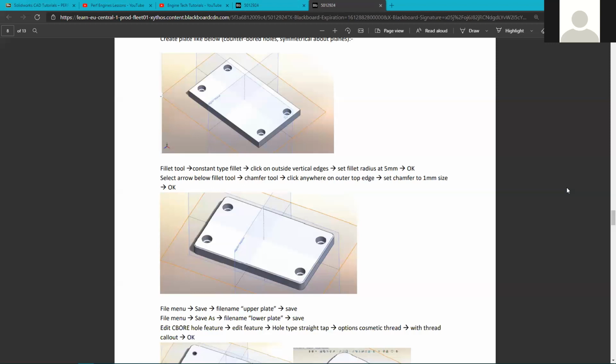But as a last ditch way of doing it, other than just modeling up a simple pair of cylinders that just represent the outer surfaces of the bearing, that would be the lowest quality version of representing a bearing. I think you can go to bearing manufacturers' websites such as SKF and actually download the SolidWorks model. So that might be worth a little look. I've done that in previous years. I haven't tried it in a year or so.